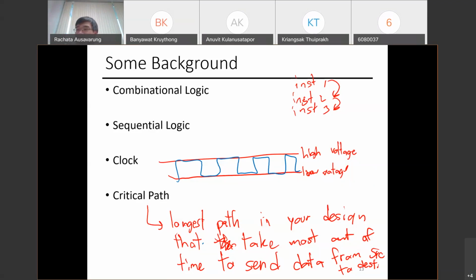Another thing that can happen when you overclock is you heat things up, right? The temperature increases. That's why when you want to overclock your machine, you need a really good cooler to cool down your logic. When you cool these components down, the critical path will shrink a little bit. This is like physics, basically. It allows you to maintain a higher clock speed without crashing your system.